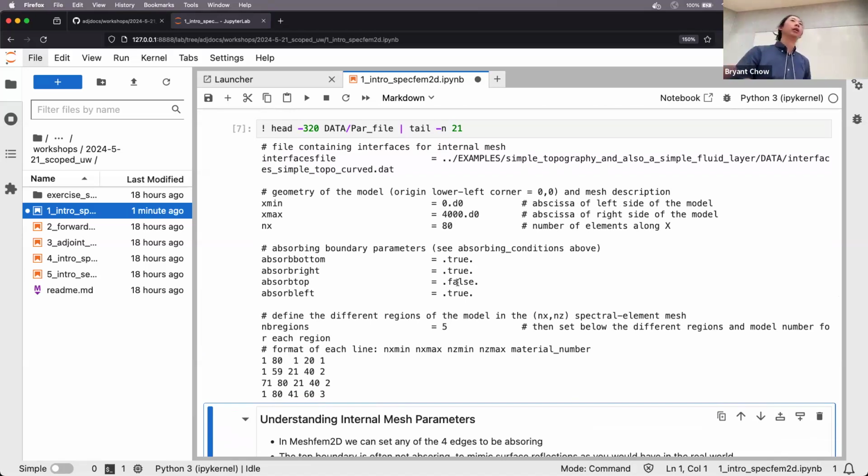So in 2D and in 3D Cartesian, you harshly stop the mesh at some boundary because we can't mesh a continuous world, or it's very expensive to do so. And you can imagine when a seismic wave hits the boundary of a mesh, if you don't do anything with it, it's going to see that as some kind of impervious boundary and it's going to bounce off and reflect. And so you'll get some artificial reflection. So in a lot of our codes, we have absorbing boundary conditions or different types of ways of treating these waves so that they don't create artificial reflections within our seismographs.